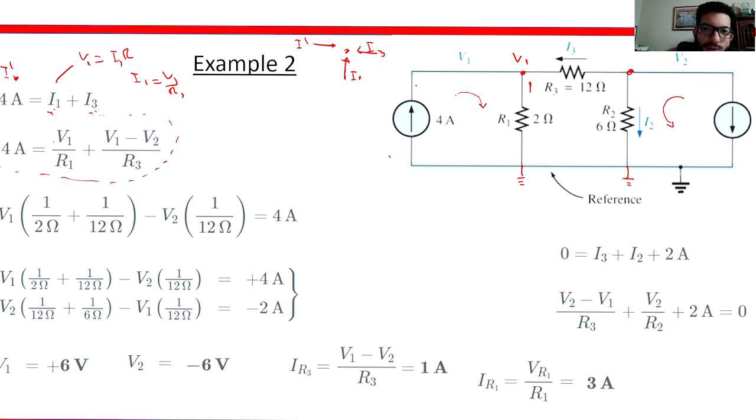So we already have one equation, which is the equation for this voltage, but we don't have V2, which we need right here. So we can set up the equation for V2 pretty simply. Let's go to this node right here, and we have that the current I3, which is this current right here, I3 plus I2, and I2 is pointing towards ground, so it's going to be coming out of this source.